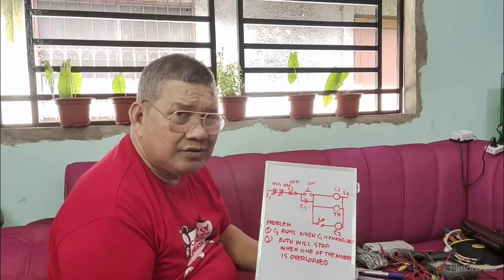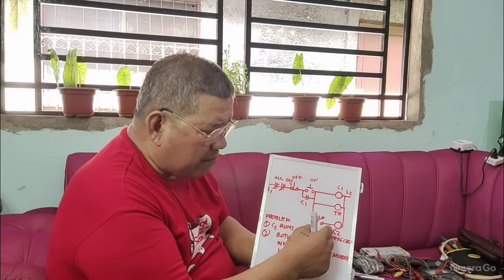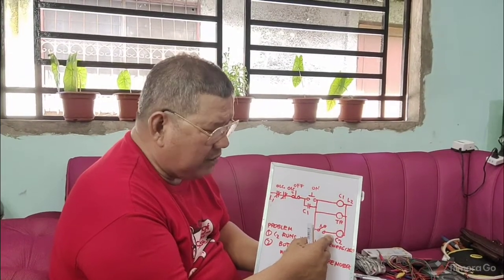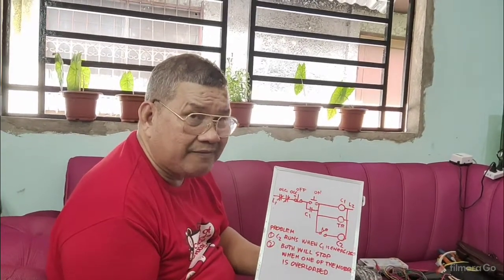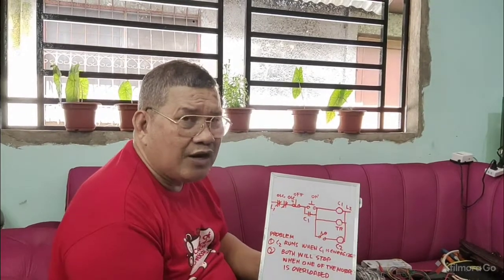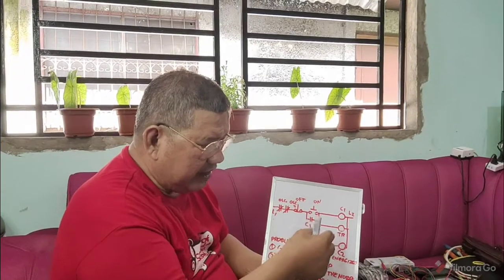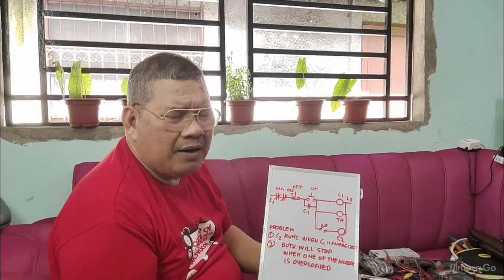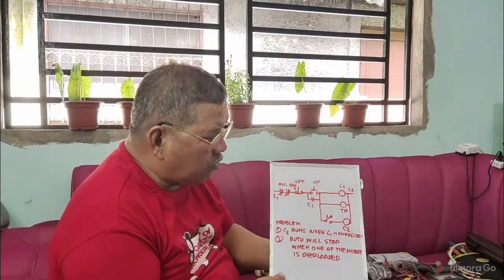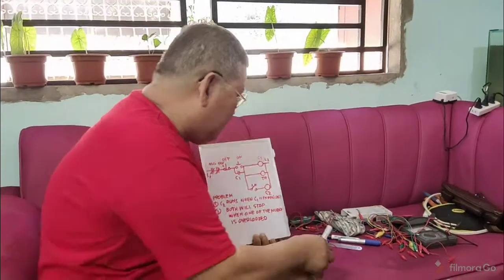So we need to change the connections to meet that condition, that when motor number 2 or conveyor number 2 is already running, then automatically the time delay relay is also disconnected from the circuit, but both conveyors are already running. What we preserve is the life of your time delay relay. How would you change this? Simple, no? Very simple.